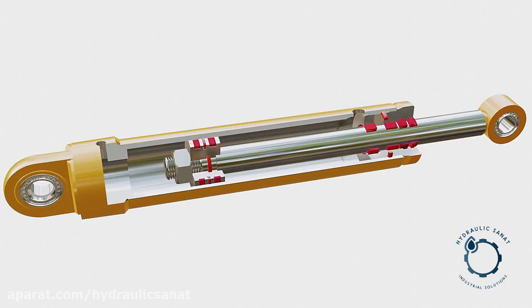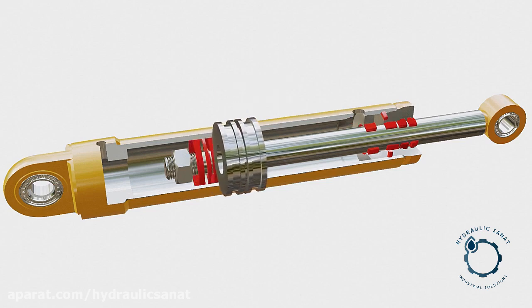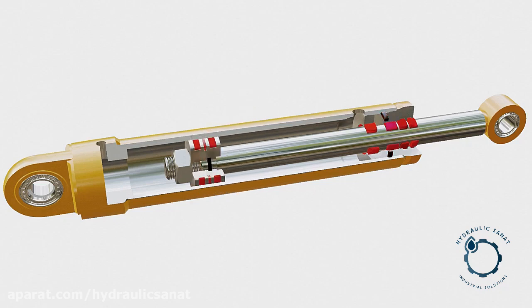A set of circular sealing rings are used in the interface of metals. These rings are assembled by making grooves in the metals. The seals used between the surfaces of metals in relative motion are dynamic seals, and those acting between two surfaces at rest with respect to each other are static seals.